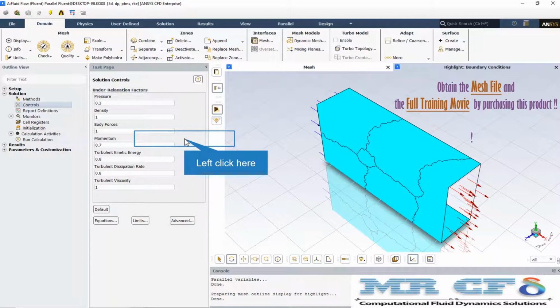These values are suitable for many problems, but for some particularly nonlinear problems, for example, some turbulent flows or high Rayleigh number natural convection problems, it is prudent to reduce the under-relaxation factors initially. It is good practice to begin calculation using the default under-relaxation factors. If the residuals continue to increase after the first 4 or 5 iterations, you should reduce the under-relaxation factors.